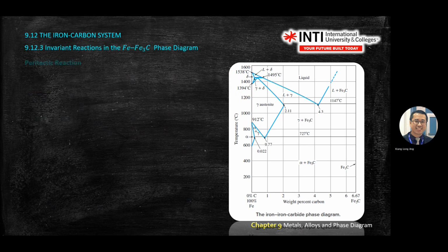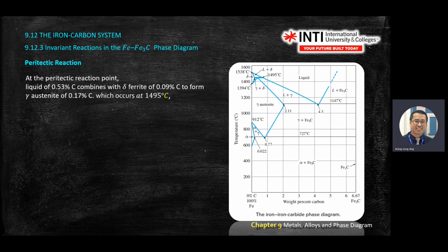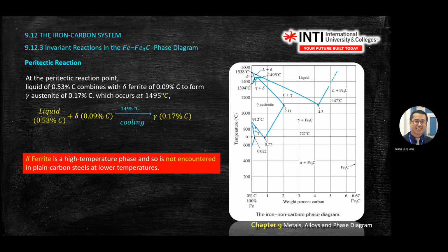Okay. Then peritectic, again. Peritectic is what? Peritectic, liquid plus alpha, you get beta, right? So you look from this graph, where does liquid plus alpha happen? For the carbon steel, the peritectic appears on the top here.